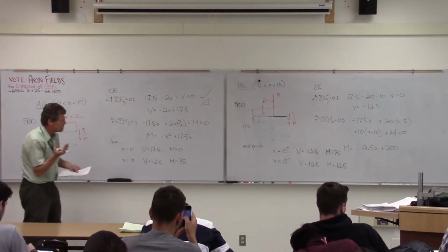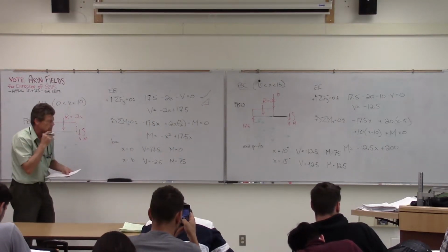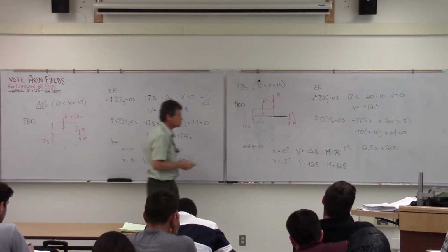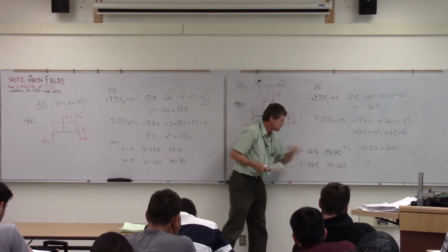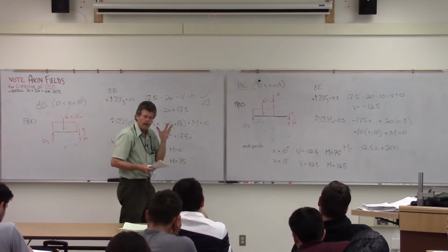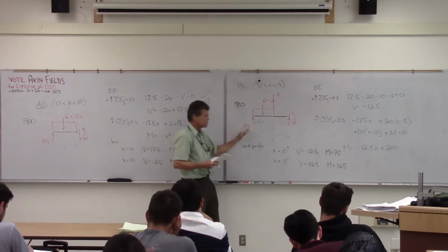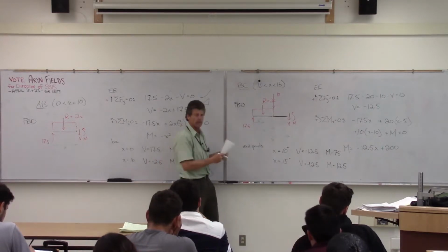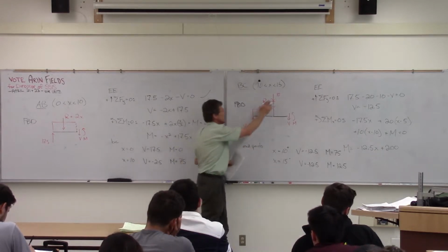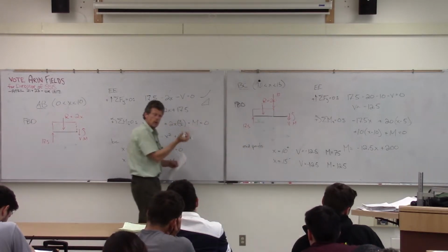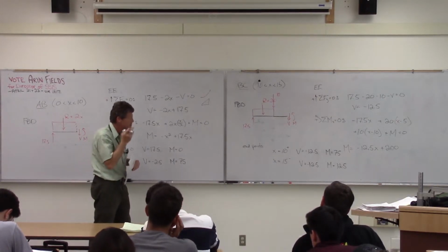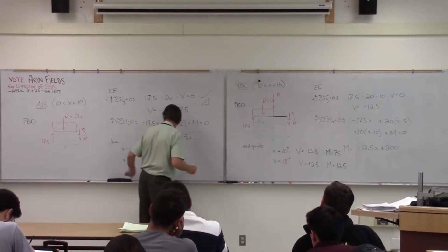And what we see is, again, the shear doesn't change, which makes sense. Nothing's happening across there. But the moment does. And it goes from 17.5 to 12.5. And again, thinking what's going on there, this 17.5 was really driving my twist in the one direction. As I start moving along there, these two start having greater moment on it, so they're going to start wanting to twist it back in the other direction there. So the moment's getting a little bit smaller as we go along there.